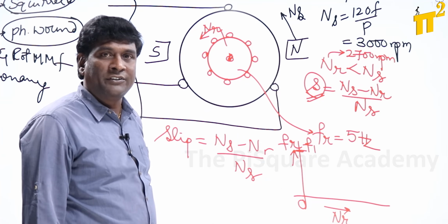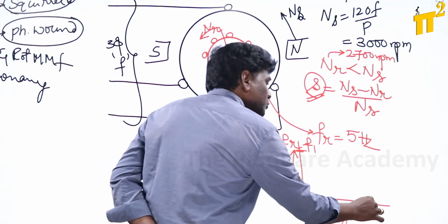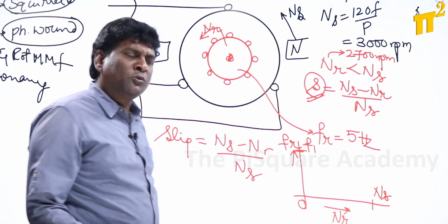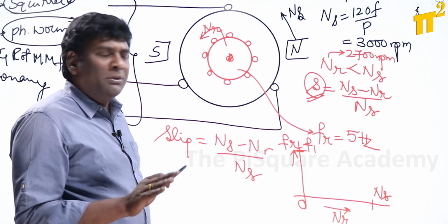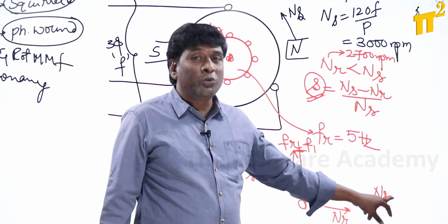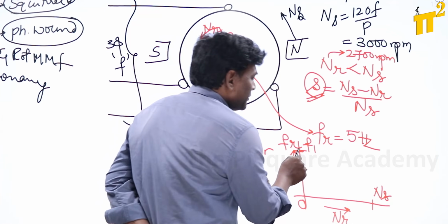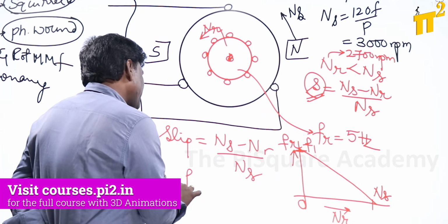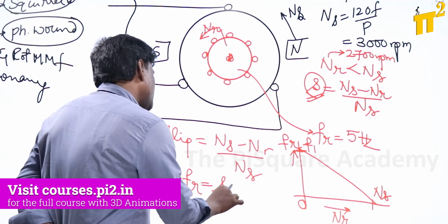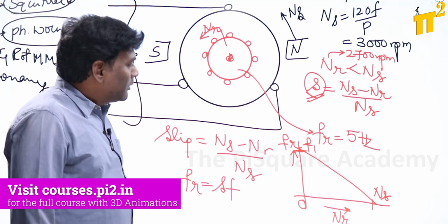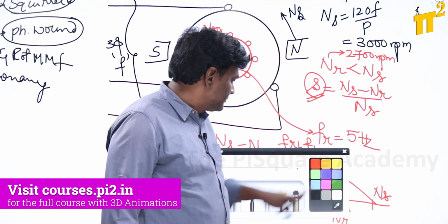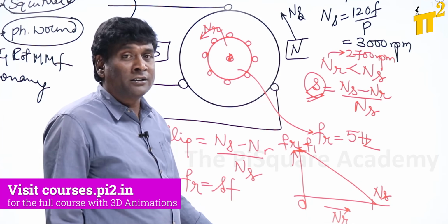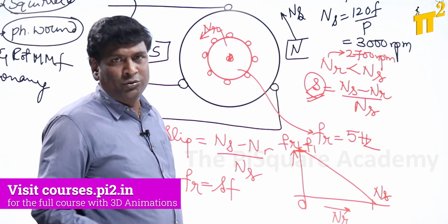That is the stator frequency only. Now, if the rotor is rotating at synchronous speed ns, of course by its own it cannot rotate, but virtually if you calculate, my frequency of induced voltage is going to be 0. So the rotor frequency is going to be s f1. The moment the frequency is reduced, what about the rotor reactance? The rotor reactance also will be reduced in the same way.